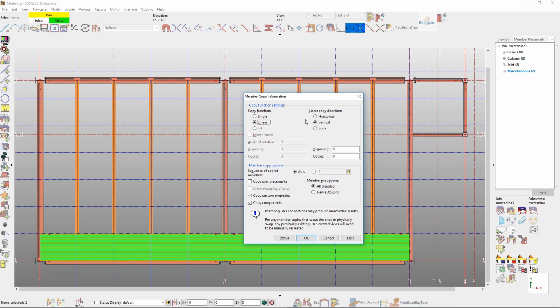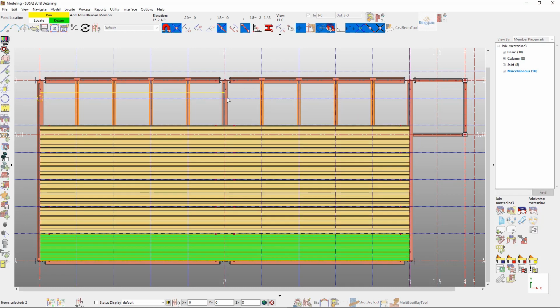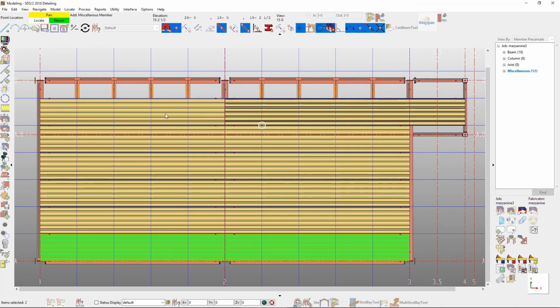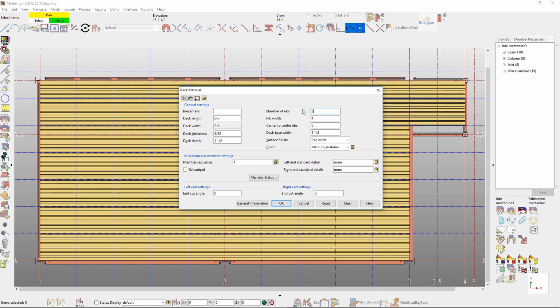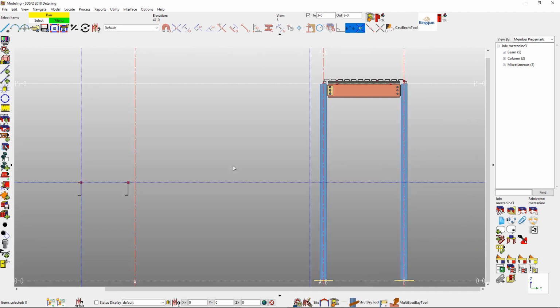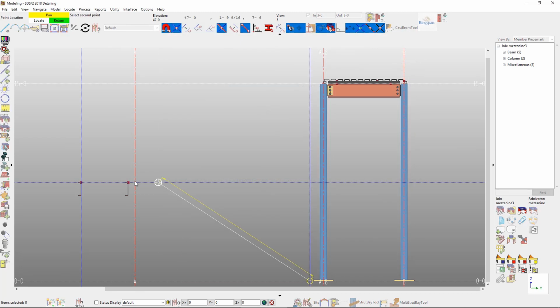By adding these items into the model, you're able to check for interferences before they're fabricated or shipped to site. This will allow for prefabrication of these items. You could piece mark and ship them to the field with all of the end cuts, copes, and banding required. This will save a very critical amount of time in the field and eliminate several field-fabricated items. This type of pre-planning helps ensure accurate quantities and proper fit in the field, making construction of the building faster. By providing an LOD 400 model, all other trades can then view and plan their work packages based upon the model you have provided.